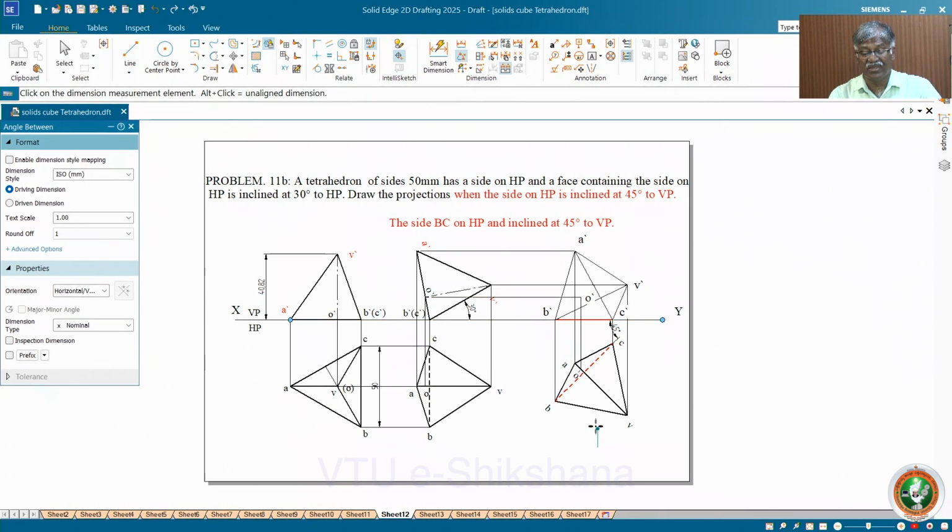How to complete this in this direction? If you look again, ABC is not visible, right? In this case ABC is not visible. Otherwise, the farthest point from you is C. Again that is confusing because C is on the ground and is connecting a number of lines. The best method is the invisible surface, visible surface, key surface method. Now if you look from this direction, ABC is not visible. Fine. You drop that step.